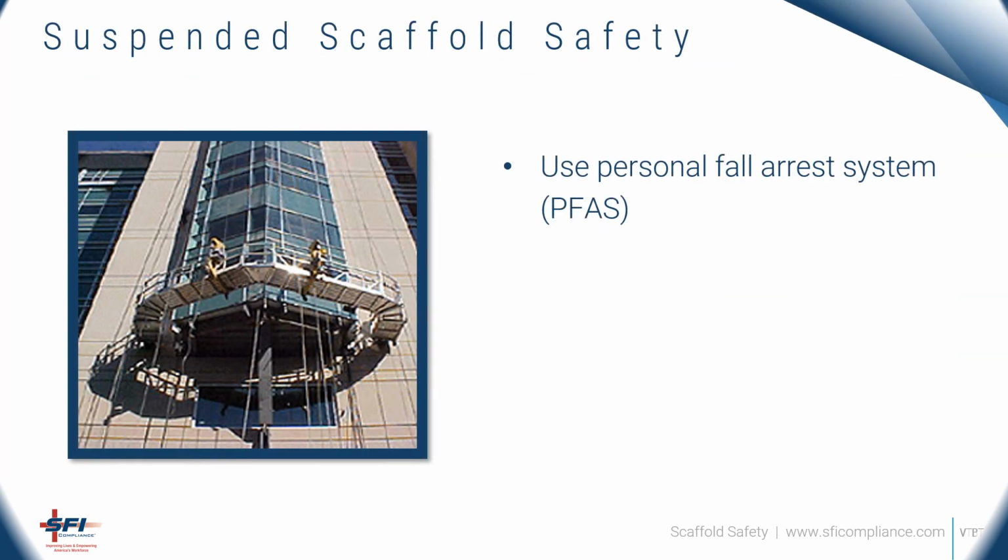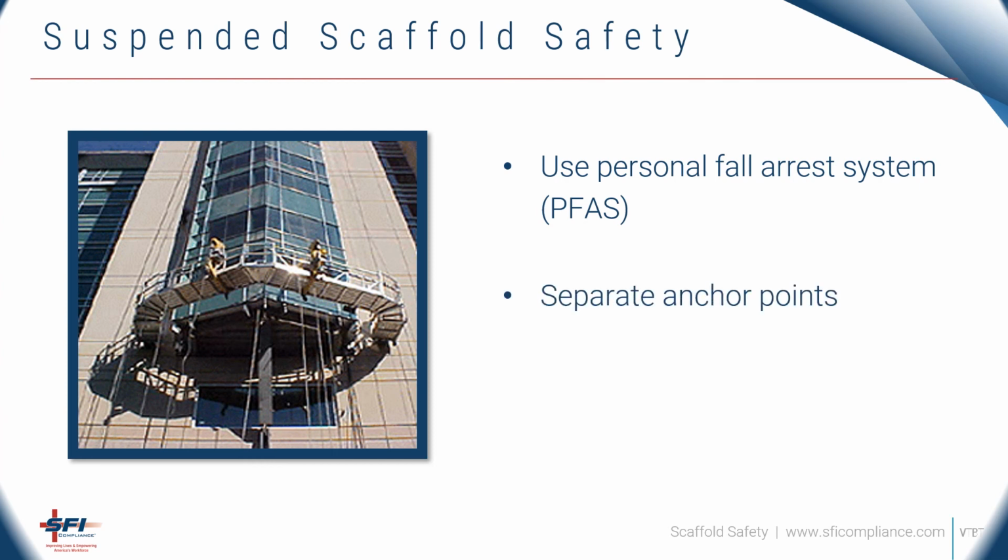All workers on suspension scaffolds must use a personal fall arrest system or PFAS. As mentioned previously, the anchor points for the suspension ropes and lifelines shall be separate. All workers shall be provided with proper training, including the manufacturer's recommendations for installing and operating suspended scaffold systems and for using fall protection. Untrained personnel should never be permitted to work from any type of suspension scaffold.